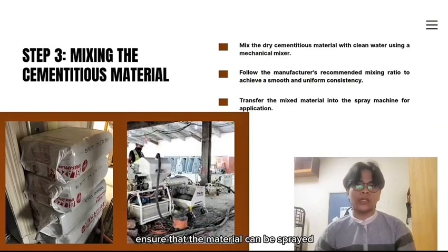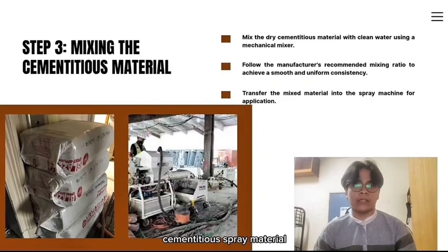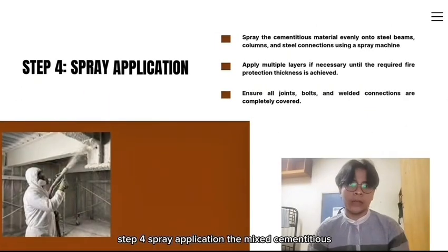Proper mixing ensures that the material can be sprayed evenly and provide the required fire-resistant performance. In the picture, we can see a mechanical mixer preparing cementitious material, and there's also a batch of cementitious spray material.